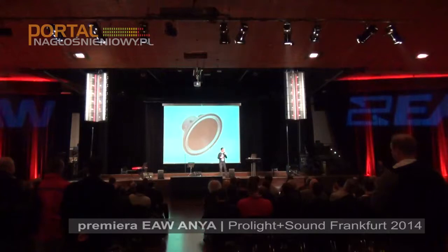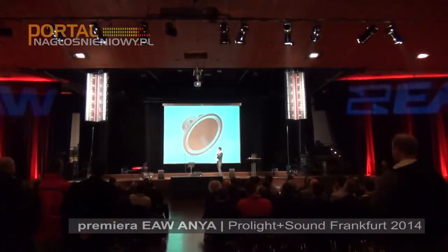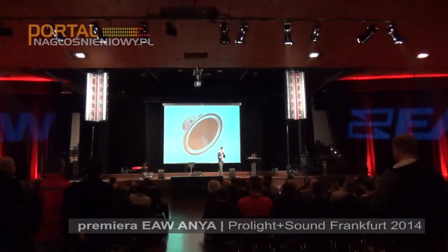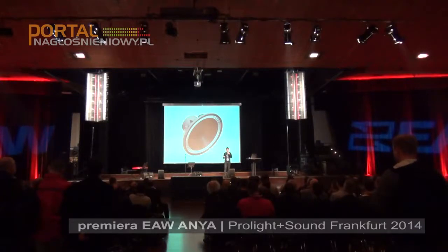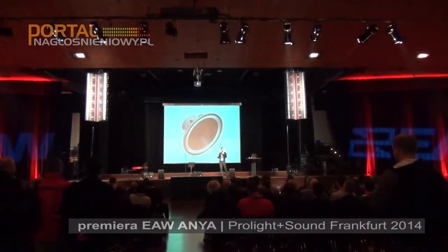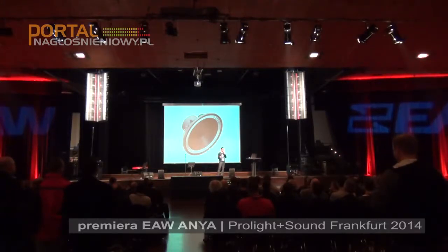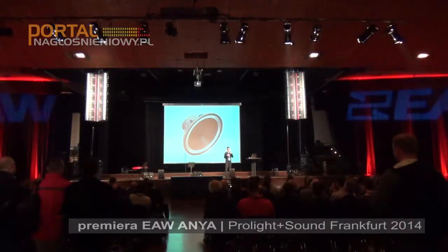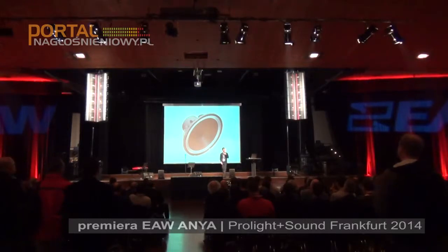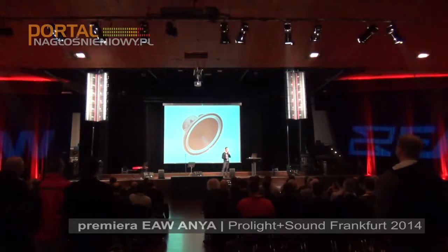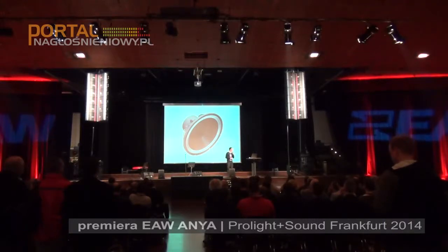The 15-inch woofer that we ultimately developed borrowed many technologies from many components that we had developed in the past. The result is a lightweight neodymium 15-inch woofer with a 4-inch coil that has extremely high excursion and extremely high output. I should also mention that the physical dimension of the 15-inch woofer was acceptable for the radical vertical adjustment that we wanted to achieve with that device. We had full capability to do that with an array of these devices over the entire operating bandwidth of that subsystem.